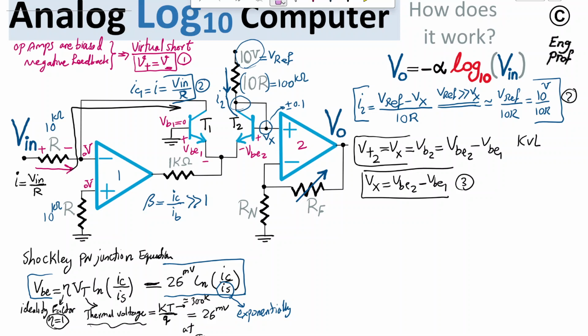So it changes exponentially with temperature. If temperature changes, let's say 10, 15, 20%, Vt changes 10, 15, 20% from the nominal 26 millivolt, but Is changes on the order of 5 to 10x. So that's very dangerous. We want to get rid of that dependency, because it results in a circuit whose output is not very accurate. So that's why the dependency is resolved in this circuit. How? Using this pair of p-n junctions that I'm going to show.